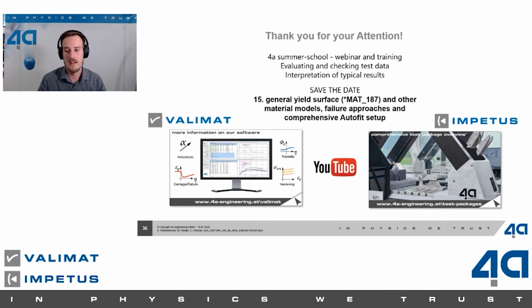It always depends on whether you have materials which will reach very high deformation. You have to think about your tensile geometry, I would say. But we typically use the type 3 specimen type, and in the test that you have seen today, we are reaching nearly 200% of local strain.